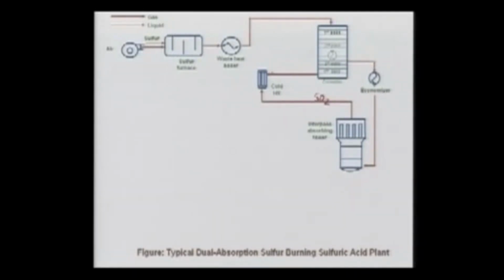We are taking a little heat from here and heating up this SO2, making use of this tower, and then you can see that we take a little stream out from there, make it hot, and pass it for the conversion. The line which you see is going back to the converter, and whatever remaining SO2 was there will be converted into SO3, and that would come out here.